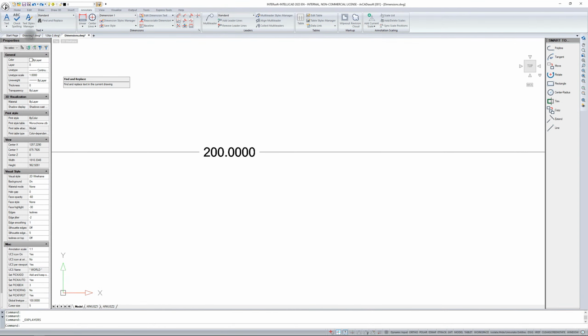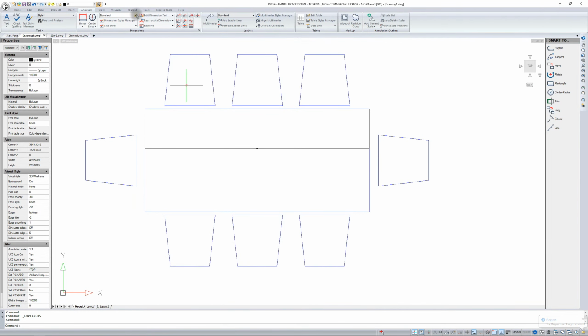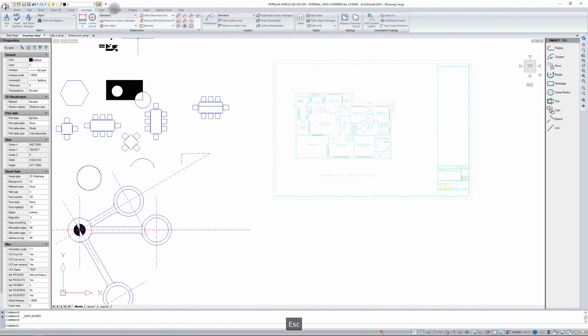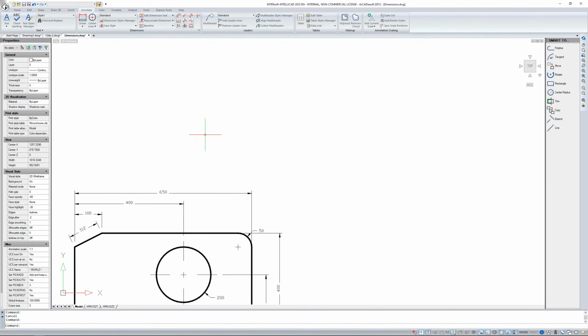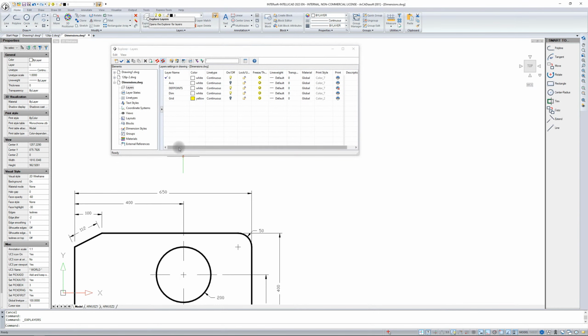Now I'm going to enter this dimension into this drawing that we were using previously. Here, I only have standard, and because I added a drawing here, which was also dimensioned, it's a bit hard to see on the white background, I would like to use this dimension style that is here, which is already defined. How to do it? I'm going to go into the INTELLICAD Explorer window, where I have been before while we were working with the text.